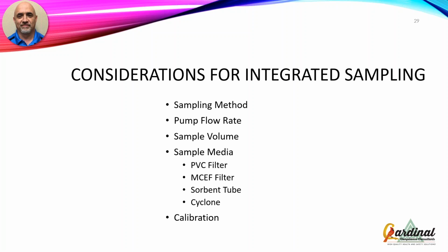With these analytical methods, there's this thing called the limit of quantification, or the limit of detection, okay? And that's the bottom line. That's the best that my method can do. What most people don't understand is that the more air I draw through that sample, the more I drive down that limit of detection, which makes my data a lot more accurate. So a lot of these analytical methods will give me an air volume between this much air and this much air, between this many liters per minute and this many liters per minute.